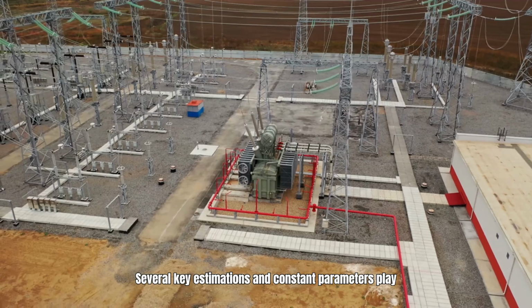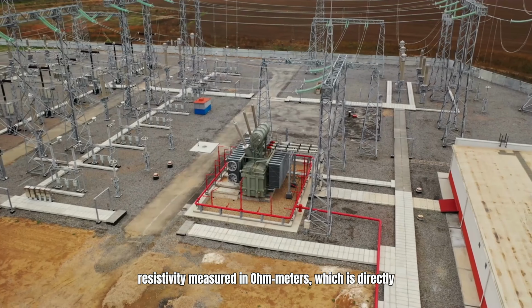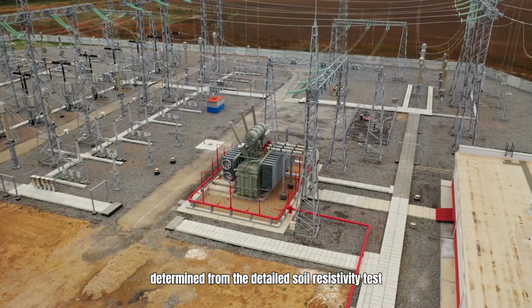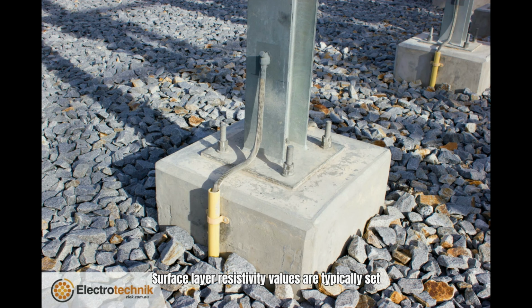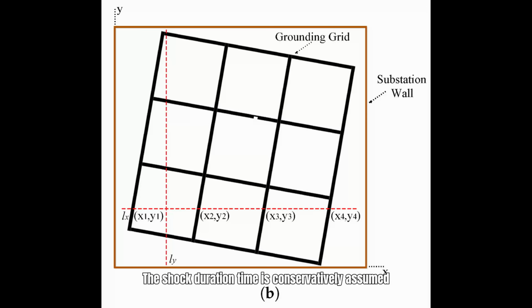Several key estimations and constant parameters play a crucial role, such as the ground resistivity measured in ohm meters, which is directly determined from the detailed soil resistivity test report. Surface layer resistivity values are typically set at 3,000 ohm meters for asphalt surfaces and 5,000 ohm meters for gravel surfaces, influencing the overall safety tolerances significantly. The shock duration time is conservatively assumed to be between 0.5 to 1 second, serving as a vital factor in all personnel safety calculations for fault scenarios.